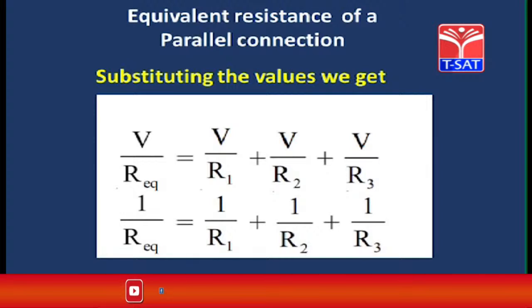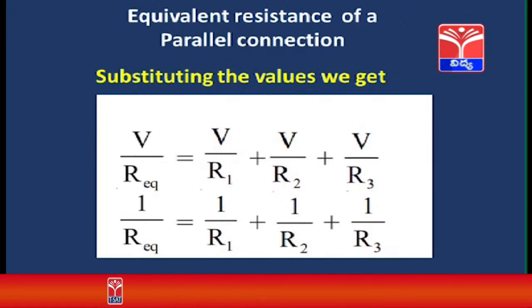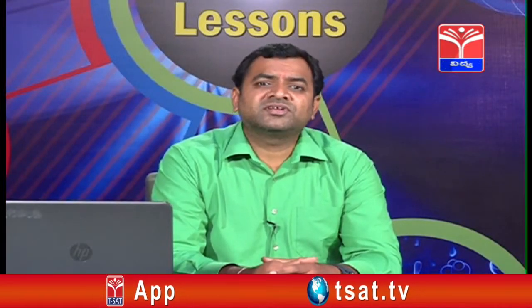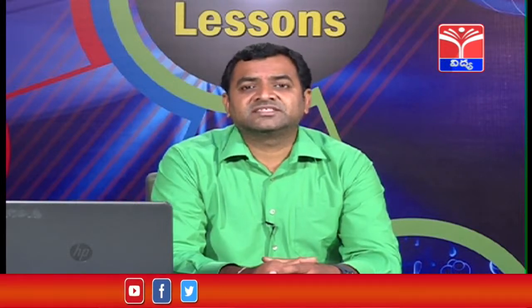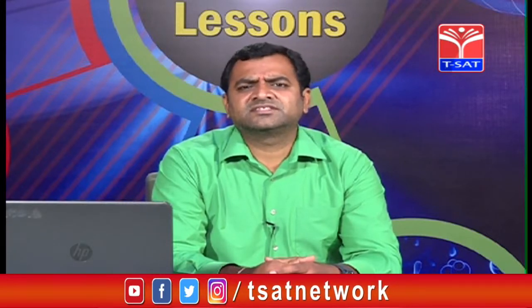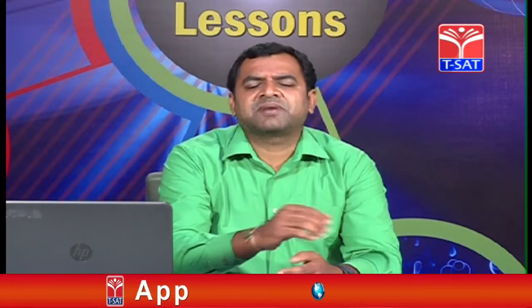So, in parallel combination, the overall resistance of the combination will be lesser than the smallest resistor in the combination. So, if resistors are connected in parallel, the overall resistance is going to decrease. That means the resistance will be lesser. So, wherever you want the resistance to be less, we can connect one more resistor in parallel.